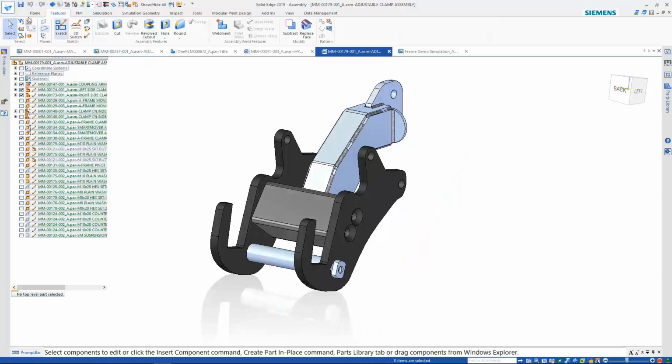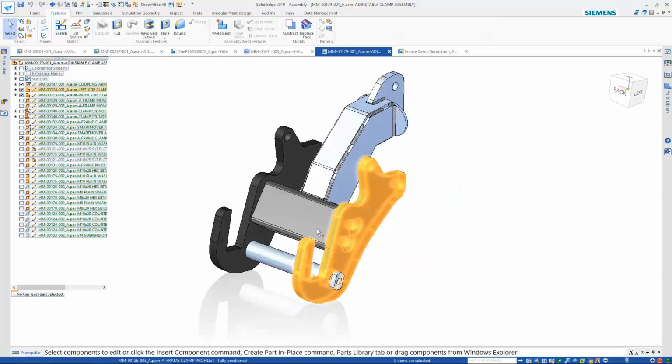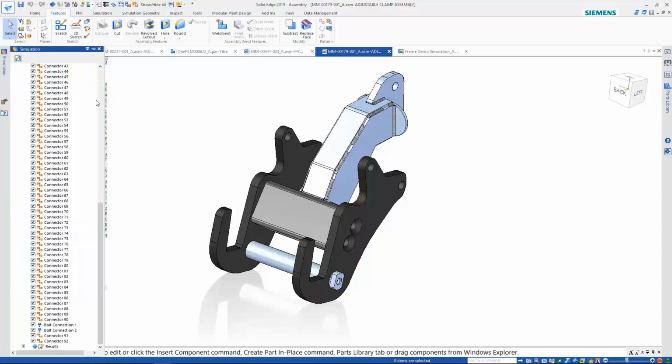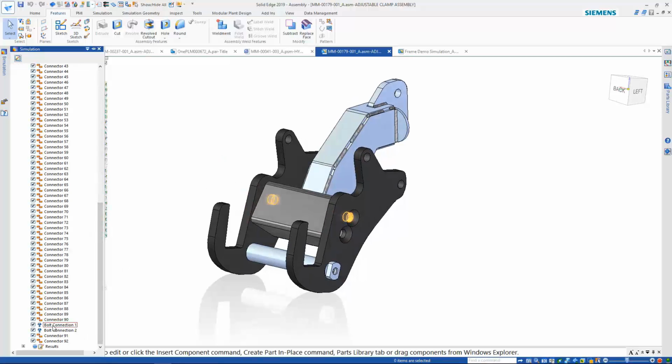So another one that we've got, we can do a full one. So on this we can use bolted. So notice we've got bolted plates on, and then we've got a welded on here. It's a little bit more complex. You can see the amount of connectors I've got connecting all these. So I've got a sub-assembly there. I've had to connect all those together first. And then we've done a couple of bolted connections on there, and then I've added a floating connection on those ones.